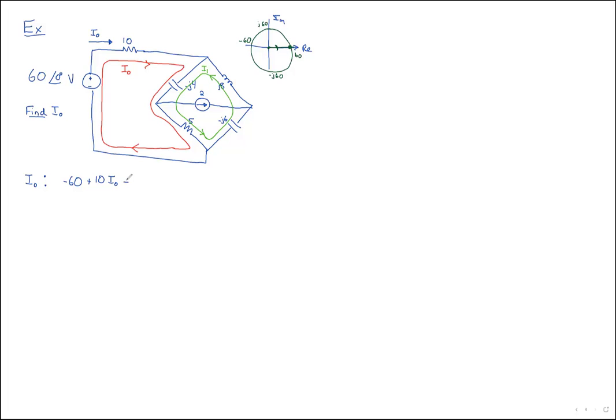And then we're going to add to it our minus J4. Over here, we've got 2 currents going through it. We've got our I naught and we've got our I1. So let me just address a question some undergraduates have, which is what current is going through this capacitor? We've drawn it as I naught over here. We've drawn this I1 over here. What gives? And the answer is that the true current going through here is both I naught and I1. I naught is just the partial current going through from this left mesh, and I1 is the partial current going through here from our right mesh.